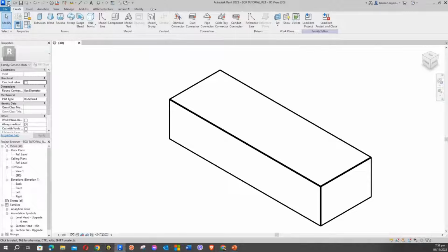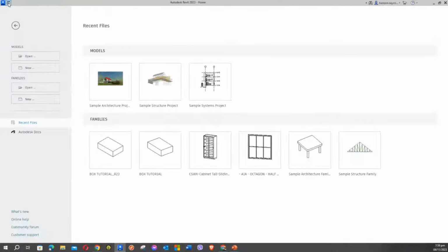So I will just need to go from here, Control D, nakalagay dyan, open a your Revit home. I will just click this or I press Control D. And this is a sample project for architecture. You can see the location if you have installed that file program. It's on the program files, Autodesk Revit 2023 samples, and that is done. You can screenshot that kung kailangan. If you need to go to that file, if you have those, or if it's already in here, just click it.